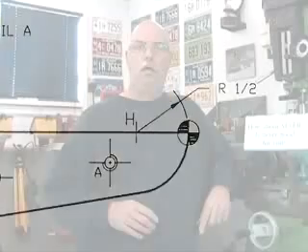And sometimes when dimensioning things such as arcs, the leader line's arrowhead can be positioned somewhere in the center of the line. Another thing that we can find on a blueprint are section views. And although they are made to simplify the reading of a drawing, oftentimes they confuse people because they're not quite sure what they're looking at. So let's take a look at some examples of sections.